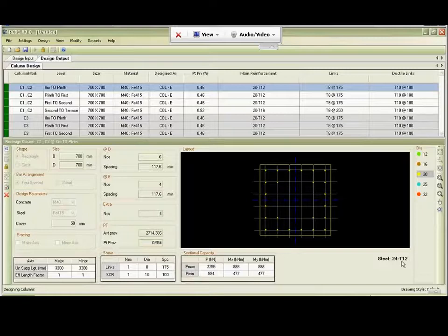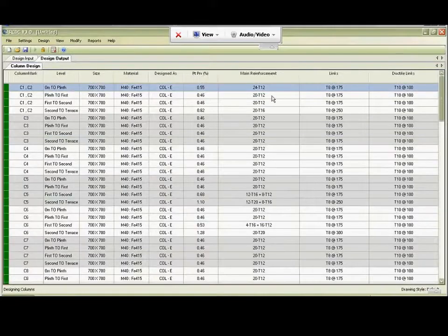So in this way you have got multiple detailing options that are available. So you can design and change detailing, design and change bar sizes, column size, bar arrangements, material property, all of it. Once I am satisfied, I can just accept it and the arrangement gets reflected here.